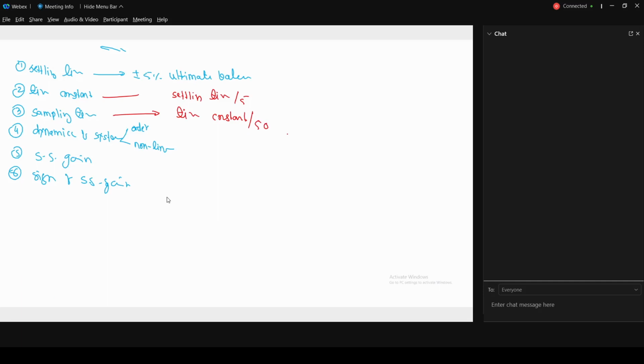So right now I'm talking about a physical system. Let's say the physical system is in front of you, and now you have changed the valve of the inlet flow rate. Correct? You change it in the fashion of a step change. How we realize the forcing functions is a different topic. But let's assume that you change your valve from position A1 to position A2, and then you wait for the system's height to settle. Once it has settled, you find out the time. So that's your settling time. Then you find out the time constant, and then the sampling time. So you understood, at this sampling time I should take the output so that I can reconstruct the signals.